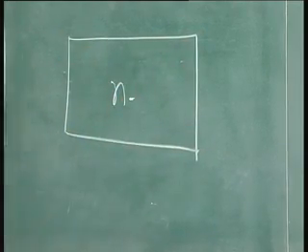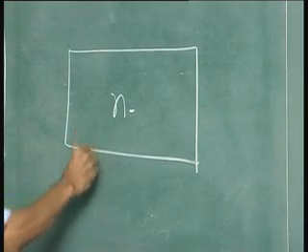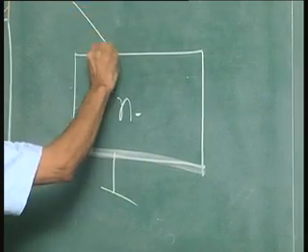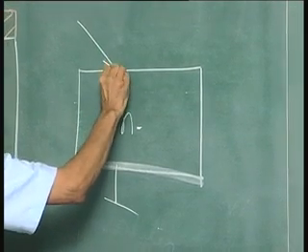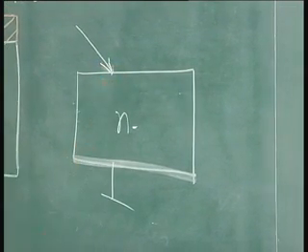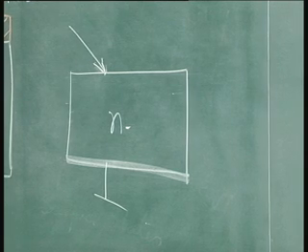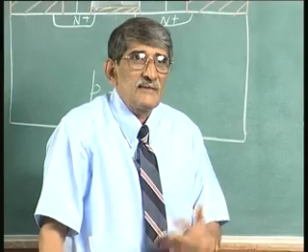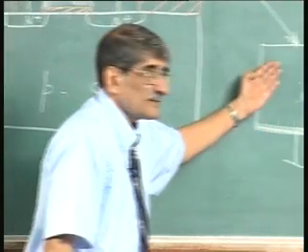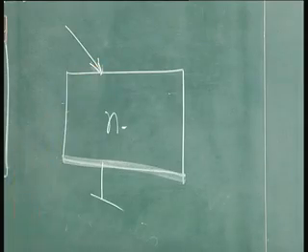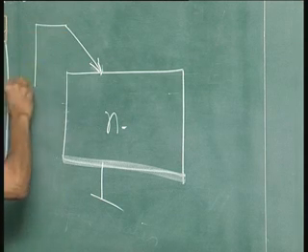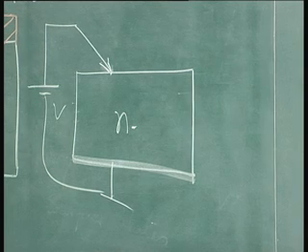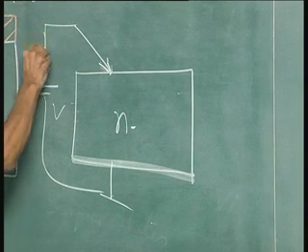N-type silicon, germanium they put. Then what they did was, they put a contact here, back side. Then they put a probe. Heat it locally, it becomes a sort of PN junction, like a point contact diode. Old days, all the detectors were point contact diodes, that type of thing. So, this is actually virtually like a P-type material. And then they applied a voltage between the two. Okay, a small voltage. Maybe they put a resistor in series, so it limits the current.